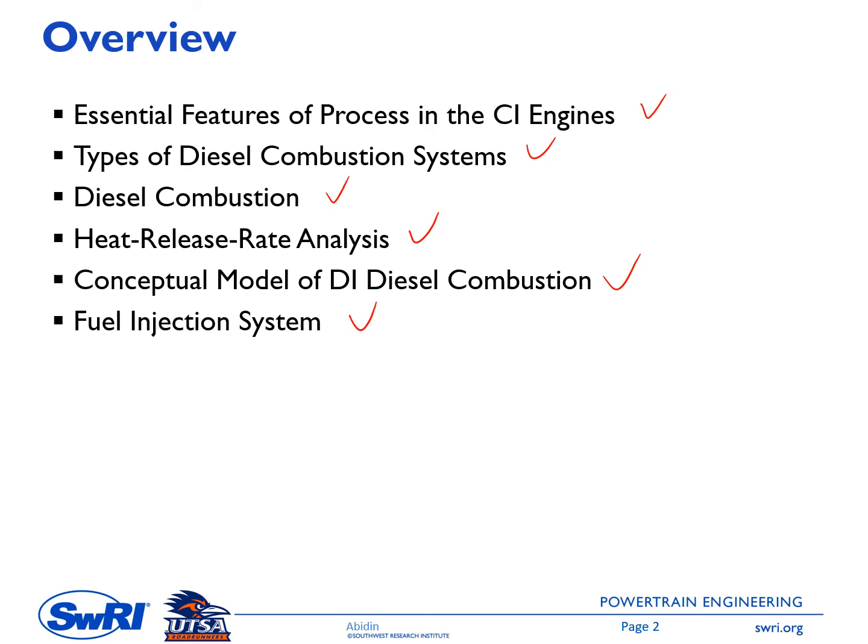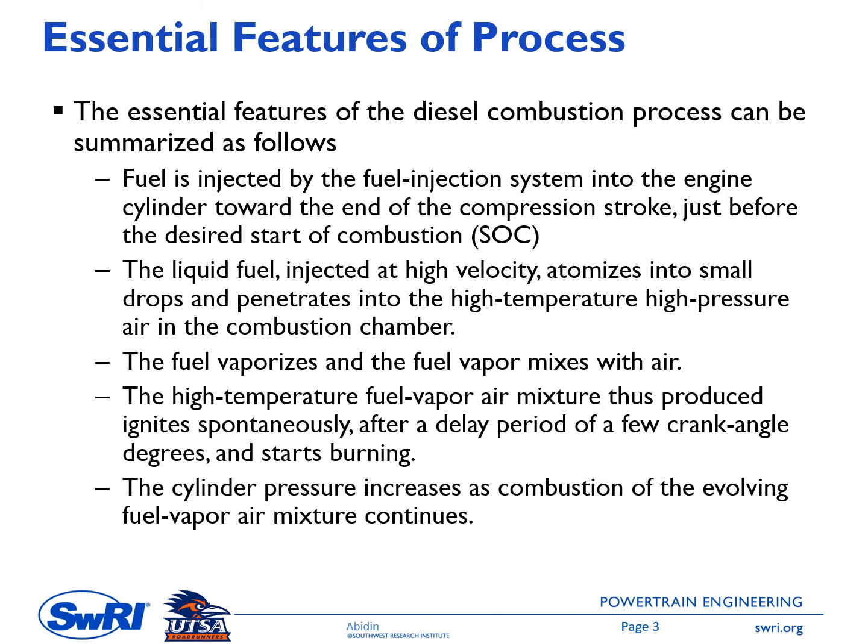Okay, now let's take a look on the first topic, namely essential features of process in the combustion ignition engines. This is the essential features of the diesel combustion process. So firstly, the fuel is injected by the fuel injection system into the engine cylinder, and usually it is at the end of the compression stroke, so just before the desired start of the combustion or the desired CA50 timing.